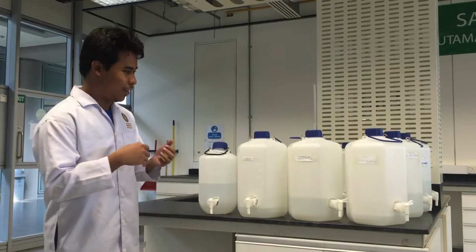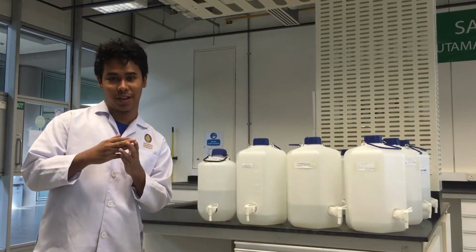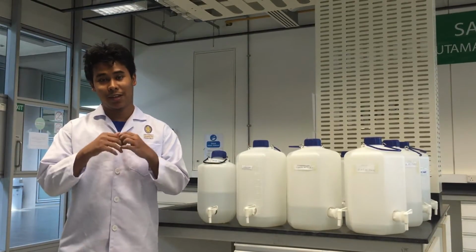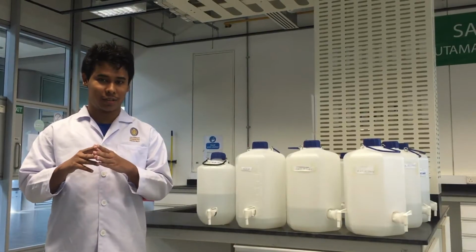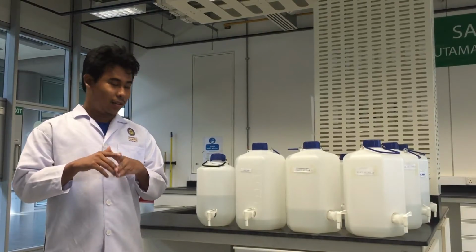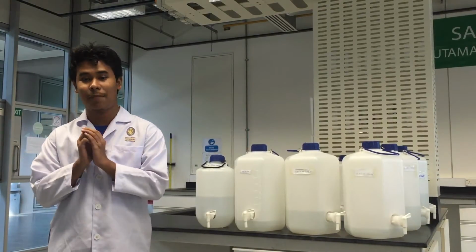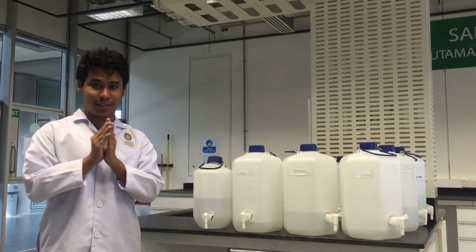To achieve the objective of this experiment, which is the batch liquid reactor experiment, we need a proper methodology or procedure. In this experiment, the methodology is divided into two parts. The first part is to prepare the calibration curve. The second part is to study the saponification reaction between the sodium hydroxide and ethyl acetate.